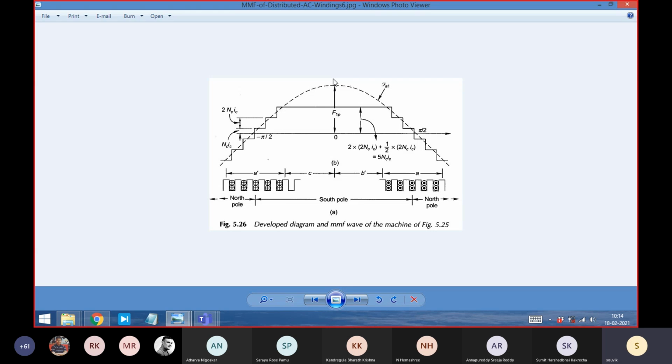Anywhere you have constructed a three-phase winding, two things are done. One is construction. By construction, you are putting coils in that particular manner: phase A coil, phase B coil, phase C coils. Okay, consciously creating their axes 120 degrees apart in space, and along with that, you are supplying current, or supplying voltage, or rather I should say current, because the MMF is related to current.